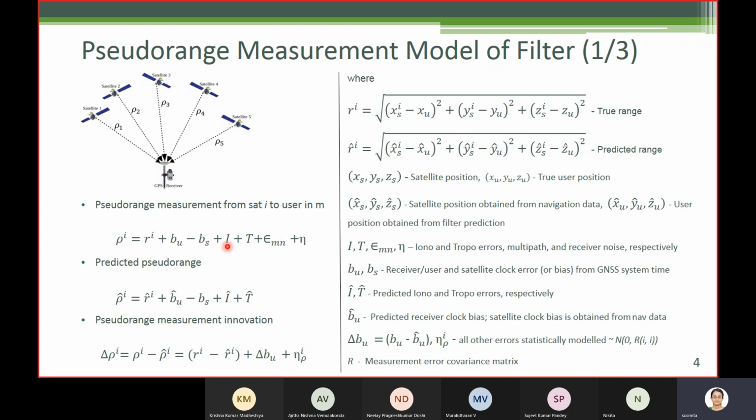I dot, generally when the ionosphere is well behaved, I dot is very small, can be neglected or clubbed in eta. Similarly, T dot can be neglected or clubbed in eta. Multipath will not be neglected. Multipath affects pseudo-range rate also. This has to be statistically modeled. Now we can ignore the dot terms for this, or we can model all of them statistically in eta.